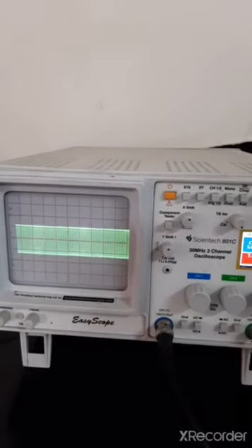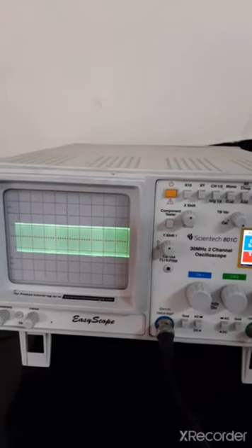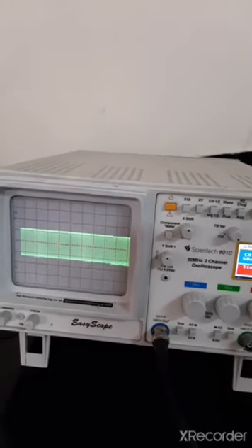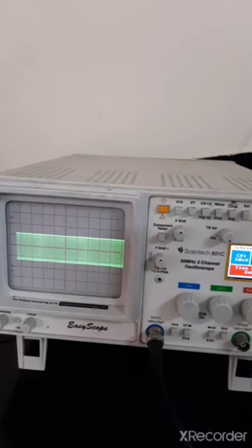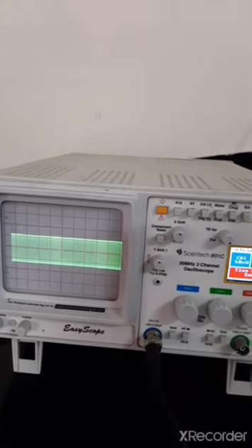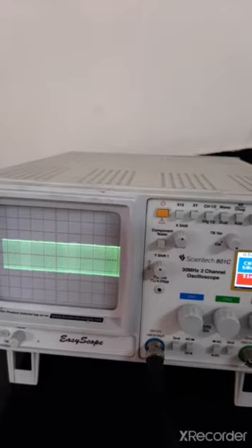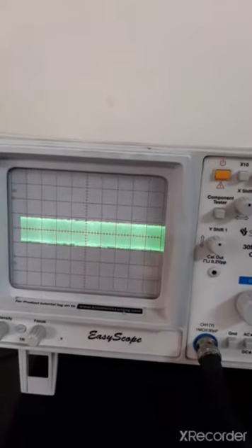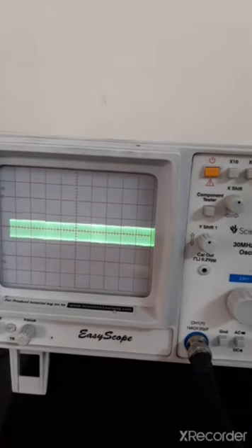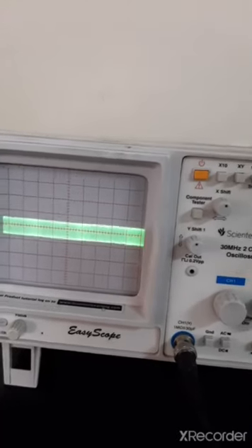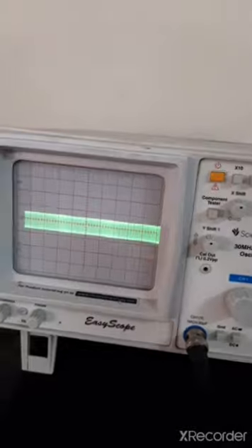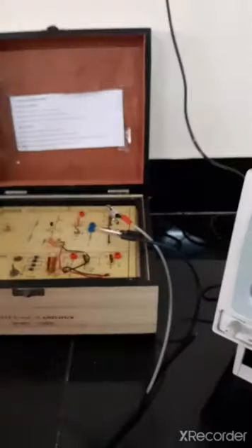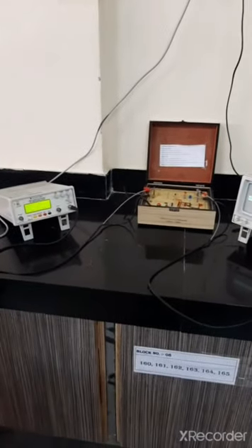If I continuously increase, you get a constant output voltage. But after the 100K, it goes on decreasing. See. Now we conclude that at low frequency, your voltage increases. At mid frequency, voltage is constant, and at high frequency, it goes on decreasing.